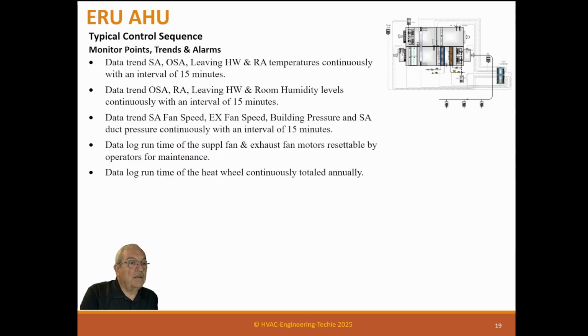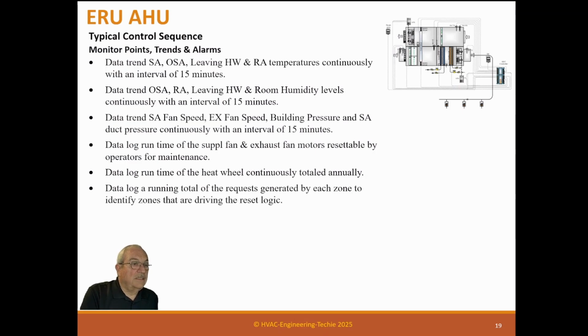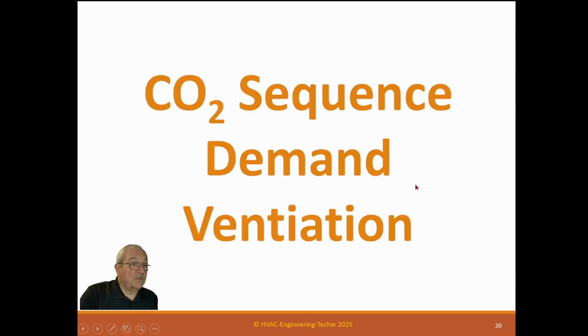Data log runtime of the heat wheel continuously, totaled annually. Data log a running total of all requests generated by each zone to identify zones that are driving the reset logic. So this is standard monitoring trends of all units.